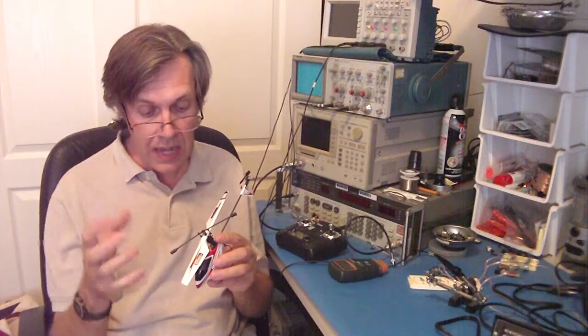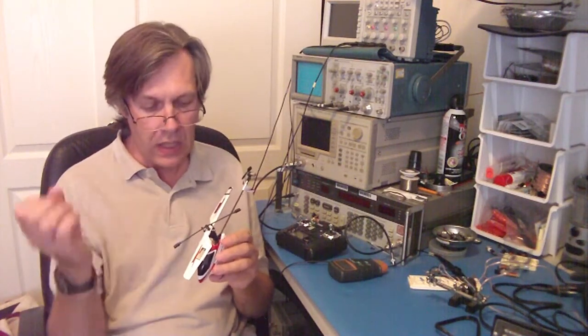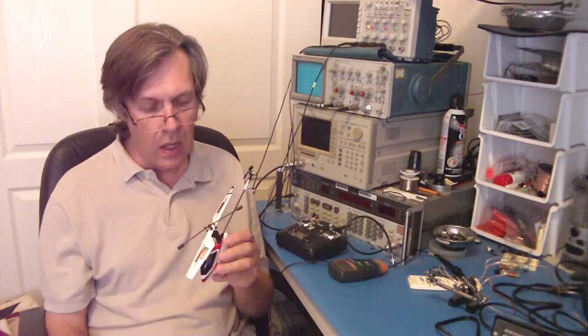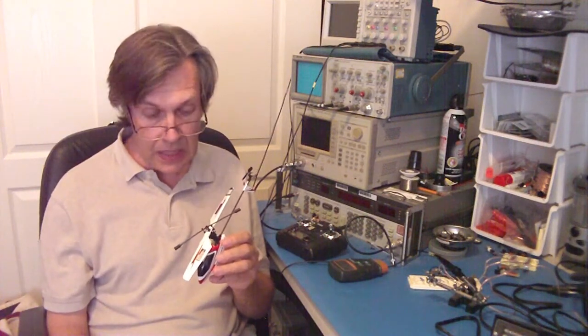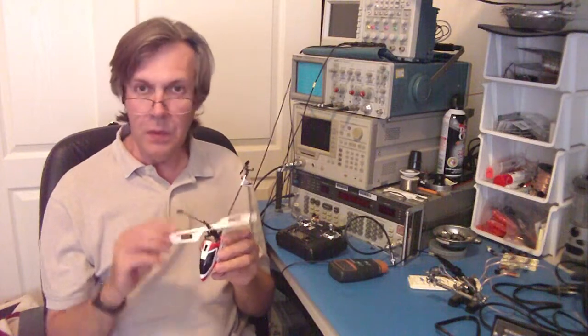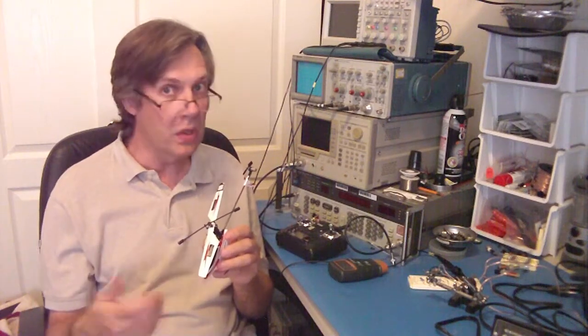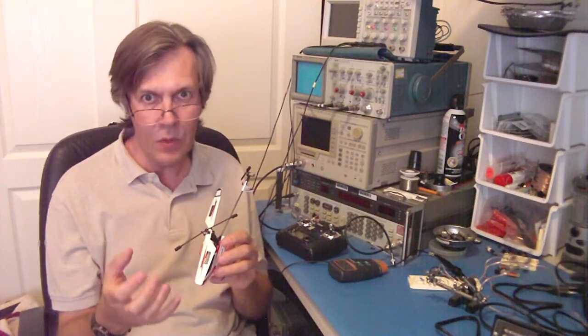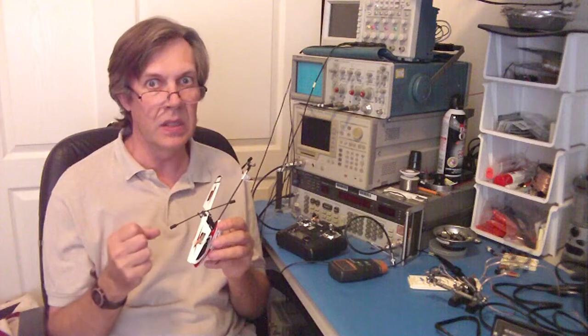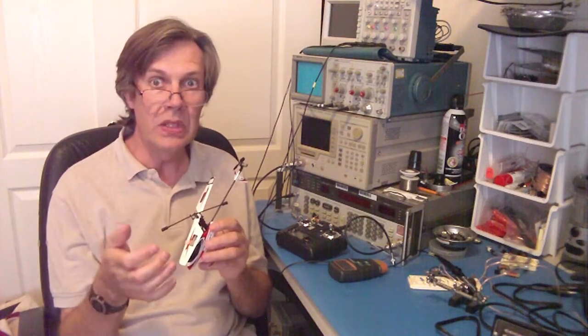If you take a snapshot and the rotor's right here, you take another snapshot and the rotor's right here, you don't know if the rotor actually did not move at all, or if it moved one full rotation, two full rotations, any integer number of rotations could have happened and gotten that exact same result. So this is why aliasing is bad in an instrumentation system, or when you're sampling for signal processing or something like that. And that's why it's called an alias, because you can have input signals that masquerade as other input signals, and you cannot tell them apart.